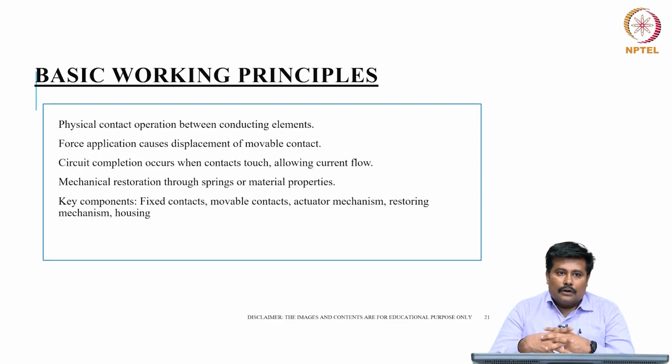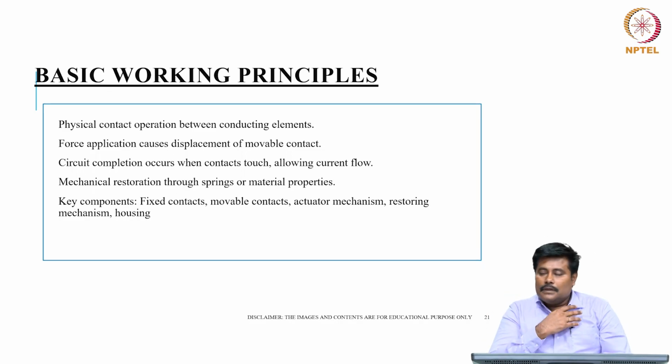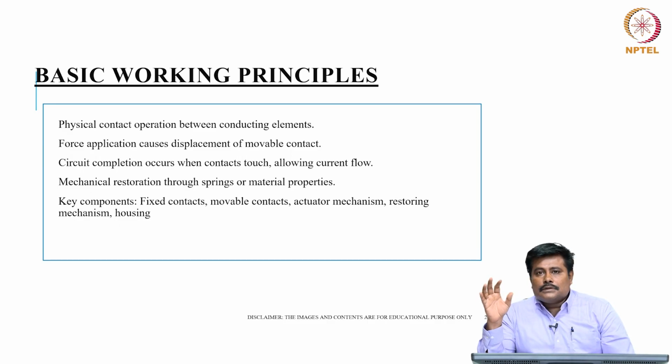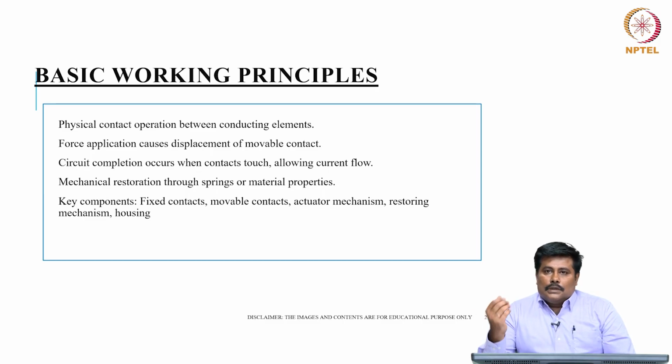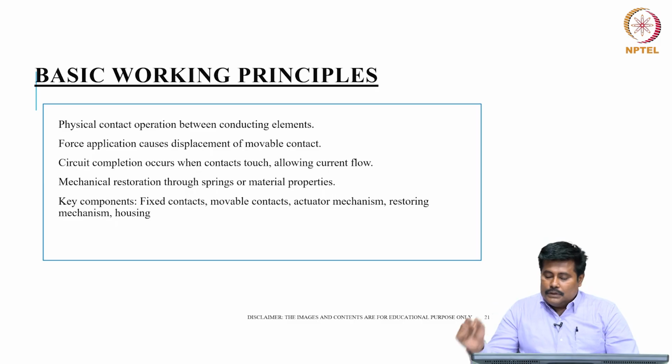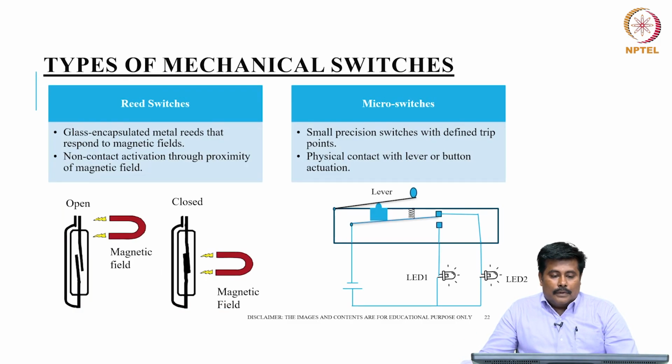As far as mechanical restoration is concerned, it is through a spring, or sometimes a diaphragm, which itself will try to bring about the mechanical restoration. So we select the materials appropriately so that this restoration is achieved. The key components are a fixed contact, a movable contact, an actuation mechanism, and a restoring mechanism, housed appropriately based on our requirements.